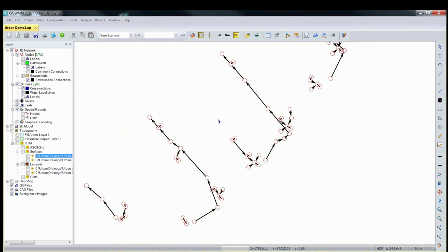The next thing that I want to do is actually look at my hydrology. And we have 3 modes to XP Swim, 2 in XP Storm. But I'm going to go to the runoff mode next and start to deal with catchment hydrology. 12D has been kind and sent me some of the information from the Drainage Network Editor, which is lovely. And I'm going to play around with that now. So I'm randomly going to select this node here.